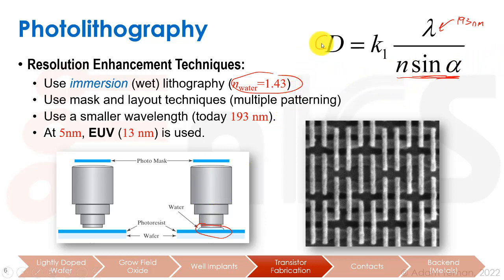But in the end, what we can do is get about an 80 nanometer pitch. 76 nanometers is usually the minimum pitch we can get. One way to do it is, for example, with phase shifting. So we use two masks or two types of slits that have different phases in them, and we can use refraction to help us get better pitches.